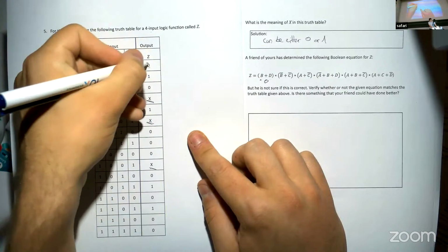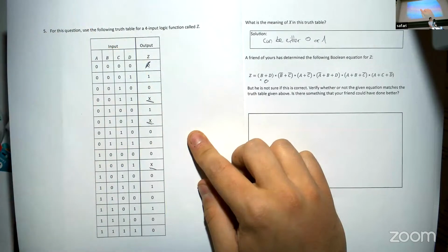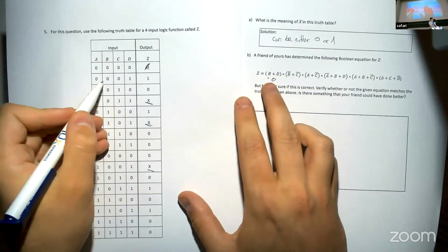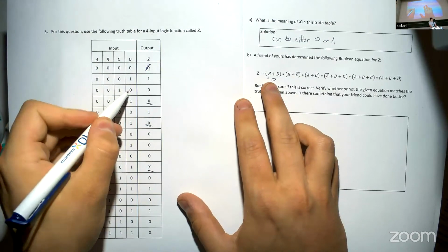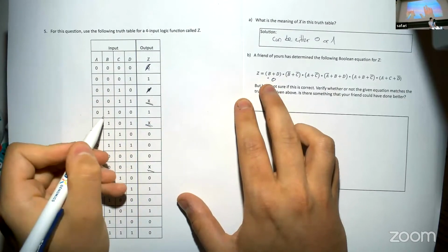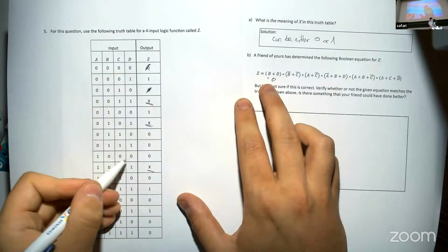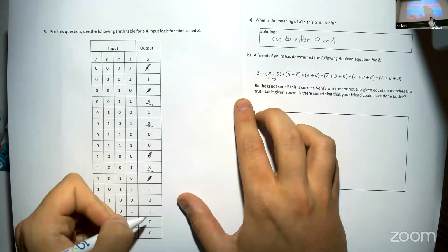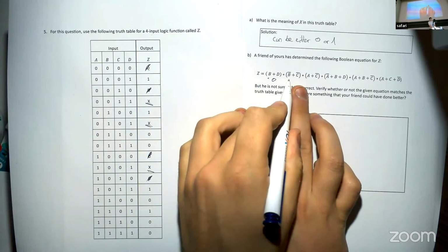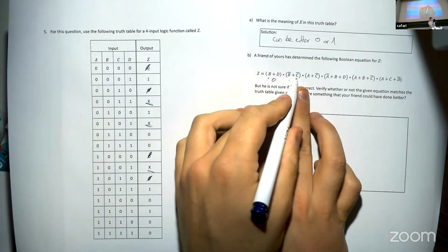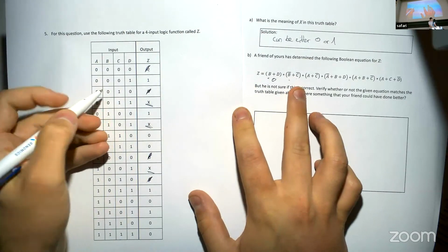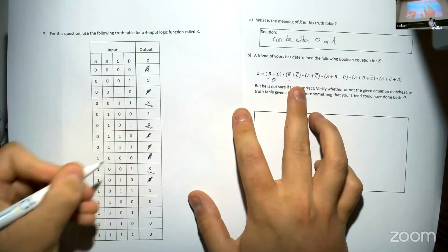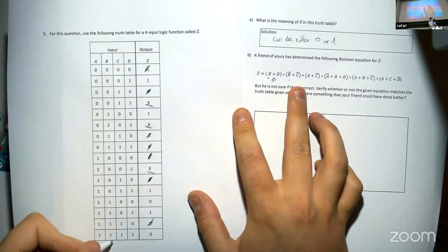Okay, so that means I'll just cross out the 0, right? This is covered by this equation. Let's find the next one. B 0, D 0 is here, okay. This is also covered. B 0, D 0 here, this is covered. B 0, D 0, this is covered. Okay. Next one, not B or not C. So this means we're looking for cases where they're both 1. So we're looking for 1, 1. Okay, this 0 is covered. 1, 1, this 0 is covered. 1, 1, this 0 is covered. 1, 1, this 0 is covered.